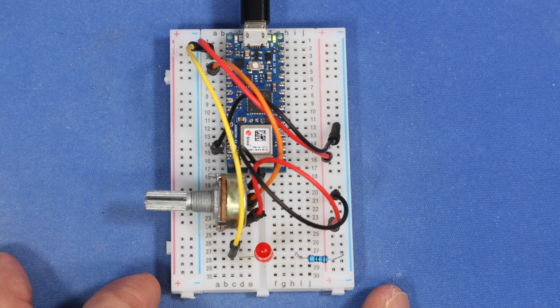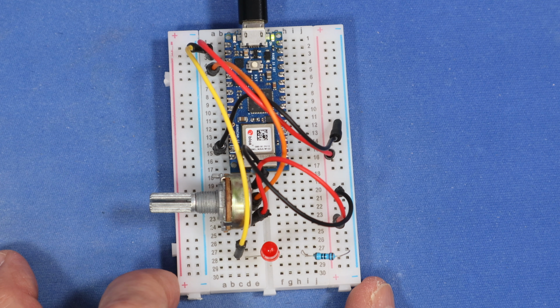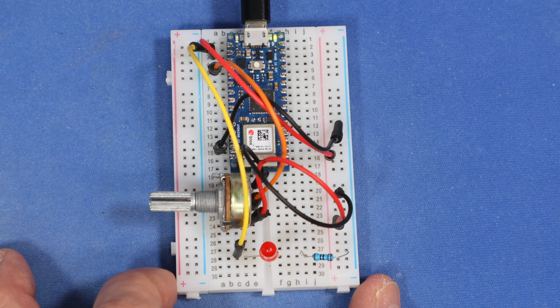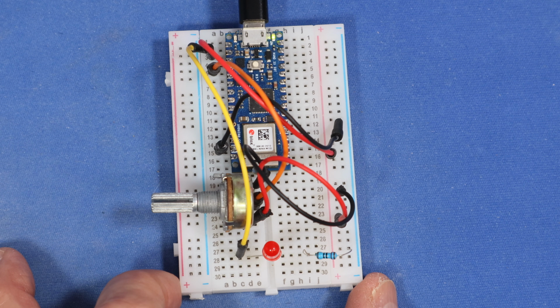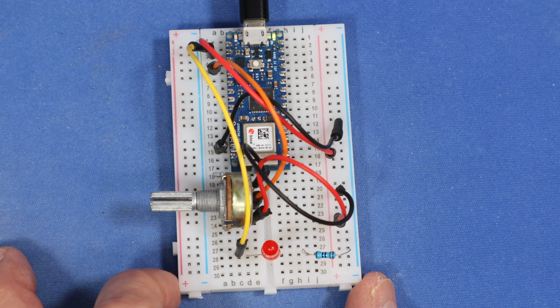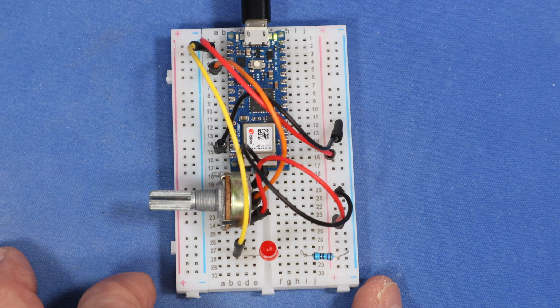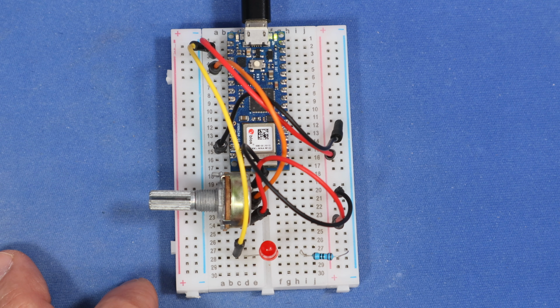Now our next test is going to be on the Arduino Nano 33 IoT, and the 33 IoT is a 32-bit version of the Arduino Nano, and it also has built-in Wi-Fi, and we've covered this in another episode of the DroneBot Workshop if you're interested in this particular processor. Now the 33 IoT has the same pinouts as the original Nano, and so we've wired our circuit the same with the LED on pin 13 and the potentiometer on analog input A0.